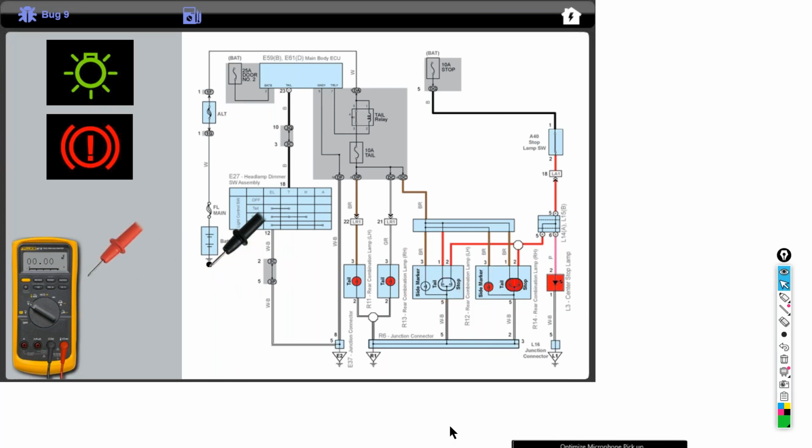But sometimes when technicians get like, okay, when you have the stoplights only on, how did the tail lights come on? And again, this is where if you use something that you can put annotations or highlight something, you can trace out how the power goes. So again, stoplight fuse, power's going to come down here, down like this, down here, and it also goes here.